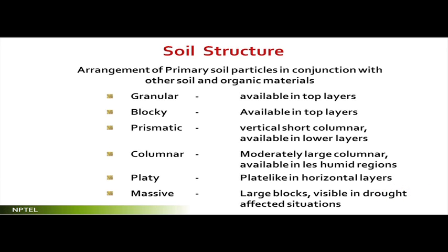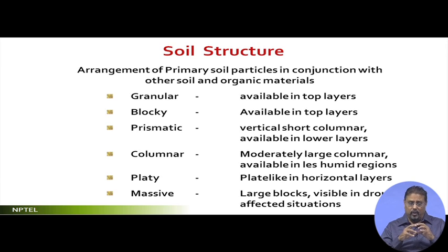If you see alluvium soils, they are quite granular in nature. If you see black cotton soil, that goes differently at different times. Now, the point is, one is the structure, another is the type of soil. The alluvium soil has a good quantity, a very fair mix, of clay, sand and silt. So maybe some layers of this will have some fine granular, but overall it is going to have a good structure.